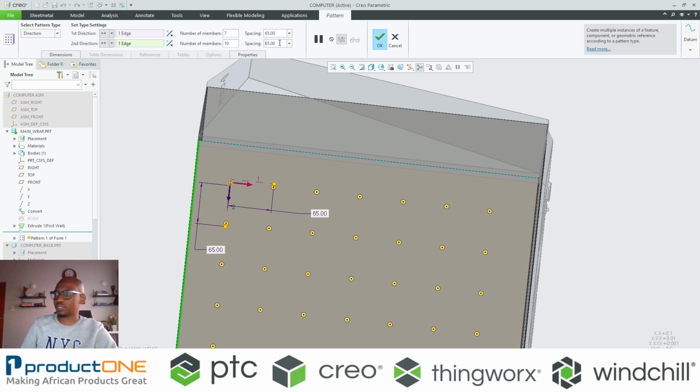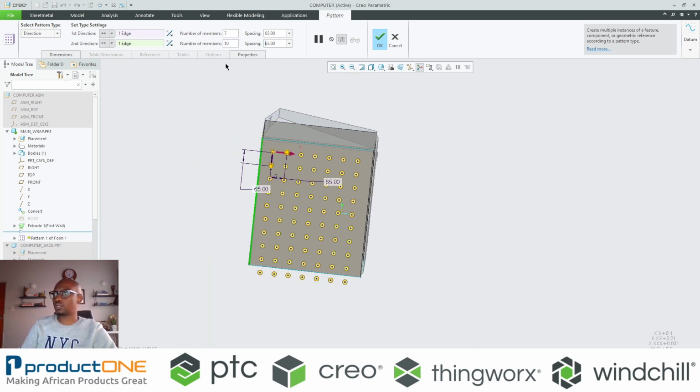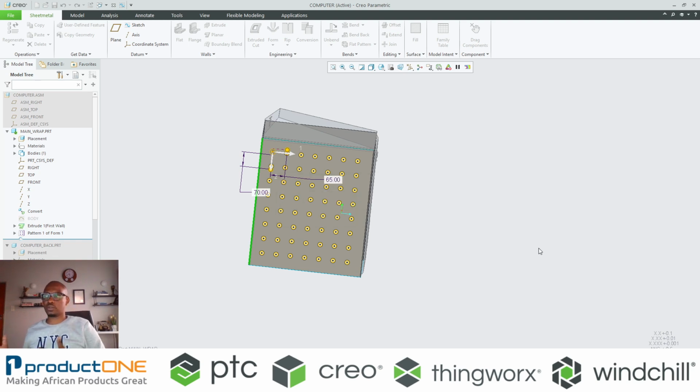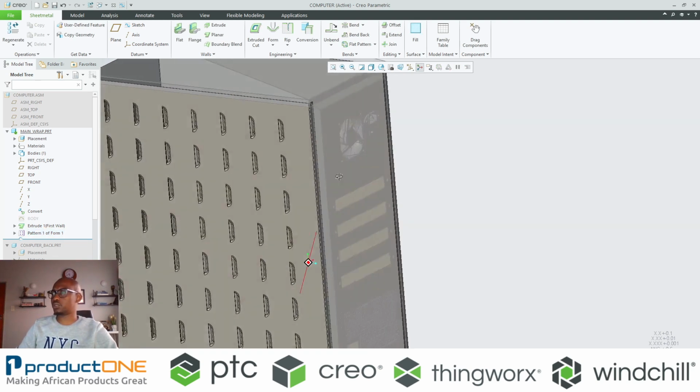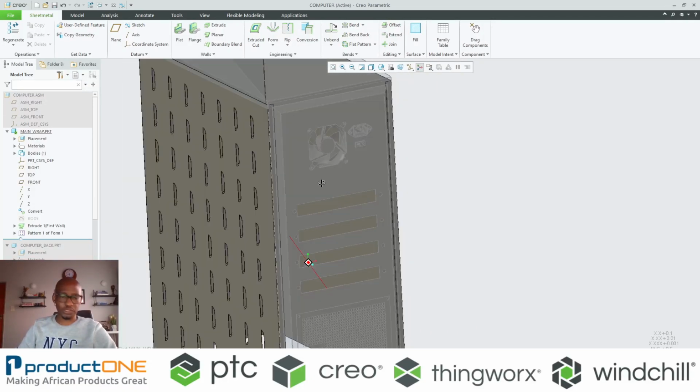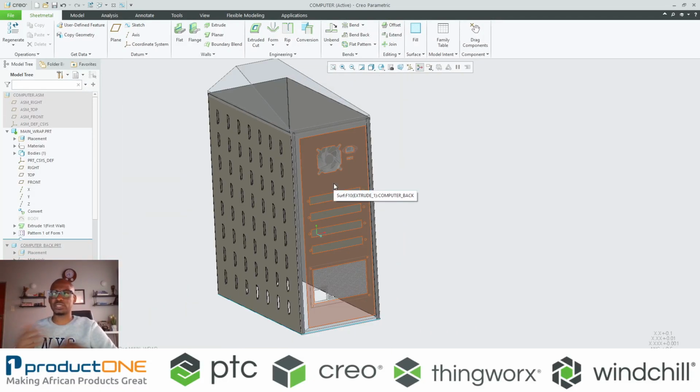All right, so I'm just essentially using 10 seems to be too much, so let's make it 8, give or take, maybe 70 on this. All right, so all that I'm doing here is creating these cutouts to have extra airways onto my sheet metal part. Of course, this is up to you.